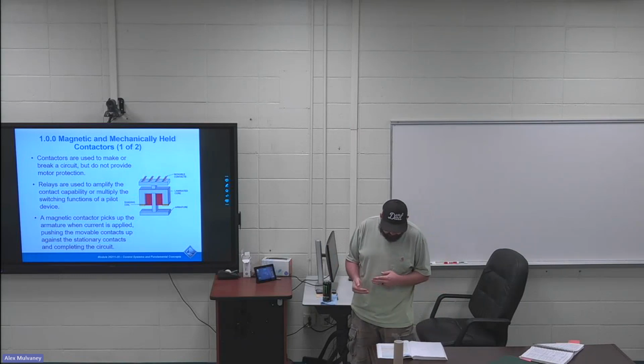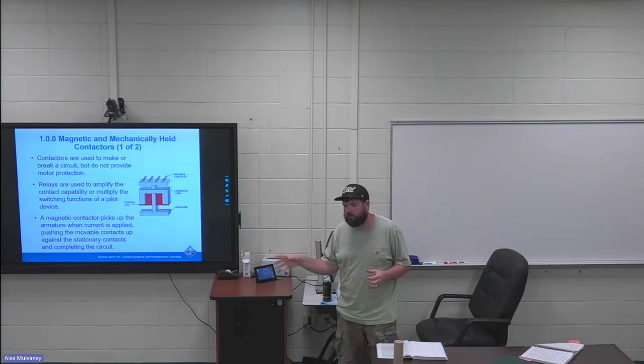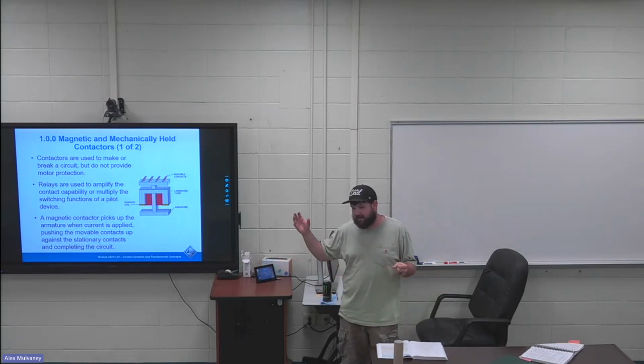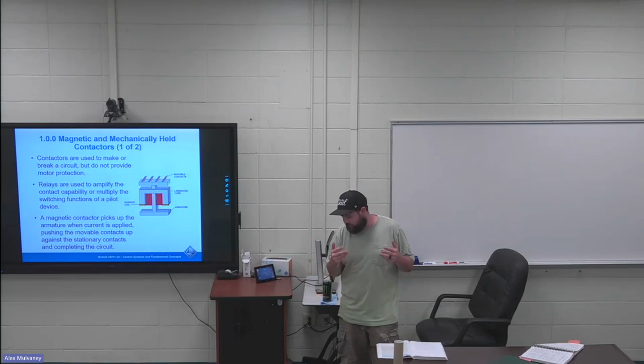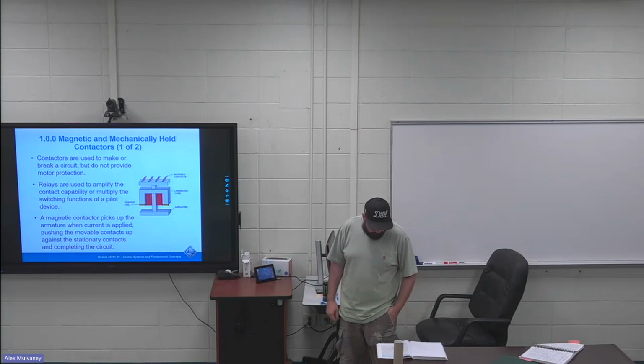The difference is the contactor does not provide overload protection. Motor starter has overload protection, contactor does not. Motor starter has a contactor with an overload device usually on the bottom. Contactor is just making connections or not, no overload capabilities.